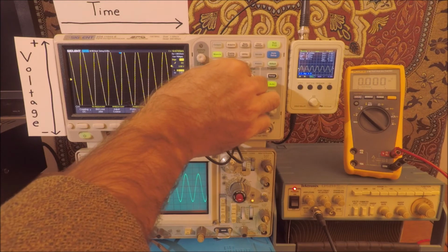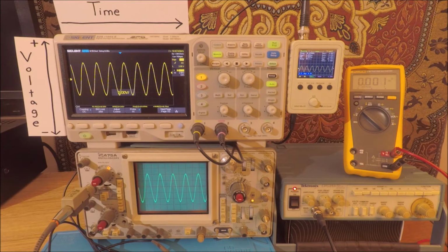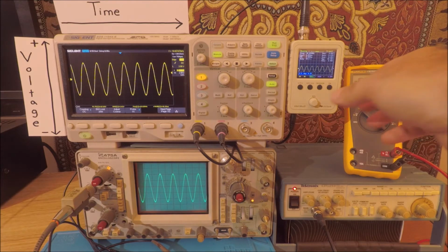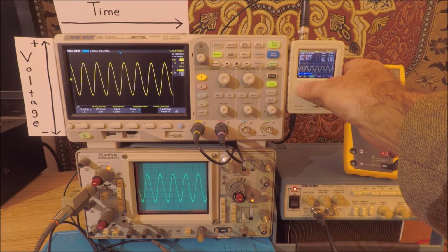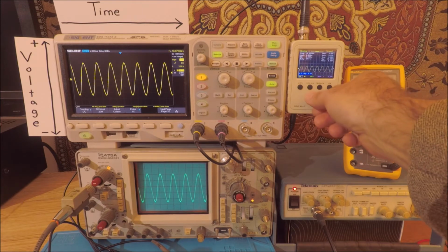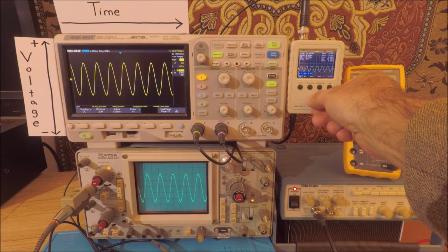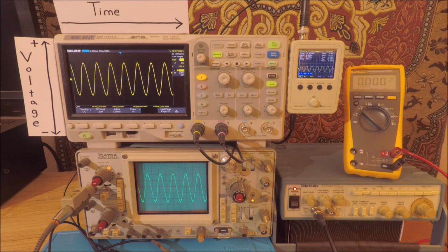So the vertical scaling control is what you're going to be able to use in order to look at very small signals and look at very large signals and be able to display both, given the size of the screen that you have. Even the small portable oscilloscope over here has the same control. Of course, there's only one encoder in this, so what we have to do is change the function of the single encoder to be our volts per division, and we can zoom in and we can zoom out on that, just the same as the larger oscilloscopes.